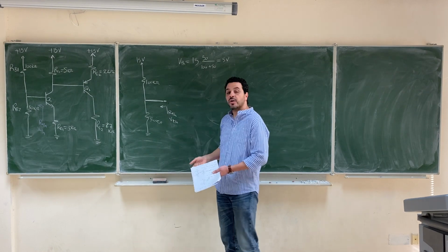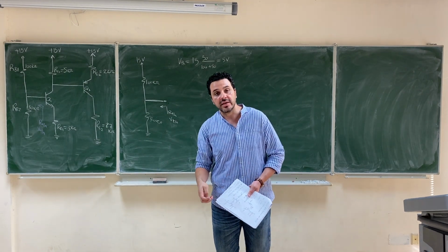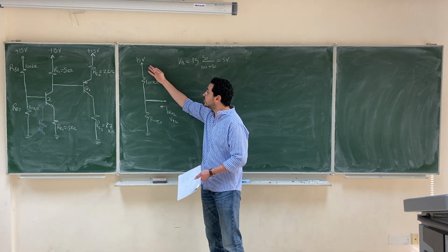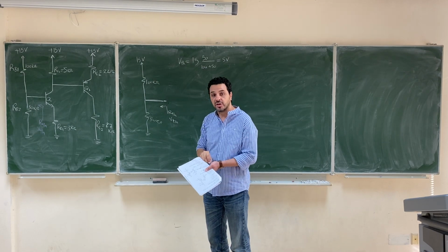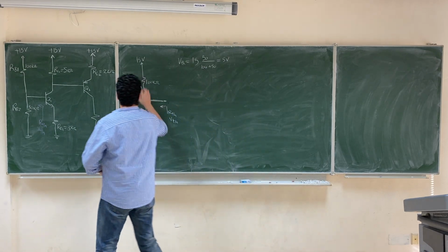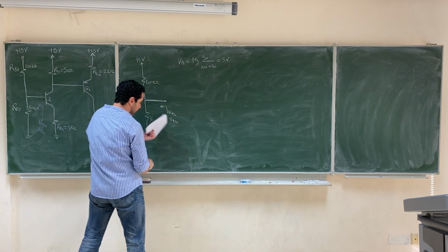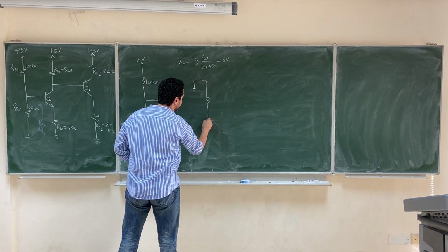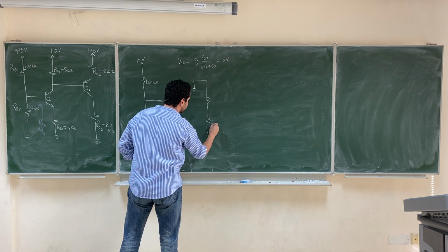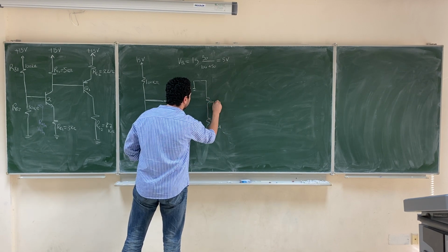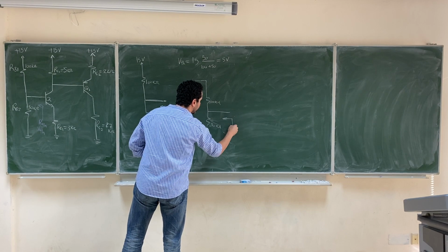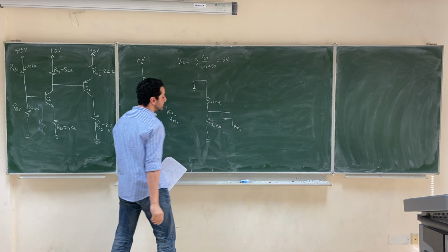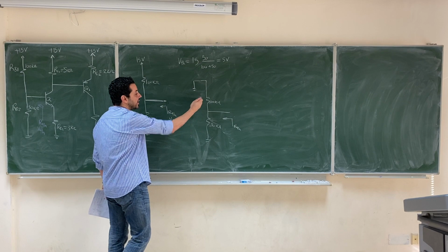And then in order to calculate R Thevenin, you remove or deactivate the voltage source. If you deactivate the voltage source, so you connect the 15 to ground, you will get a structure that looks like this. This is 50 kilo ohm, 100 kilo ohm. And looking from here, what is the resistance that you will see? You will see 50 parallel with 100.